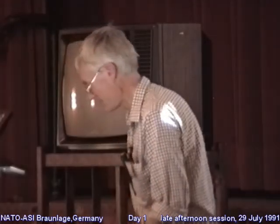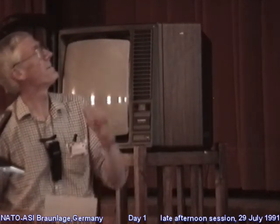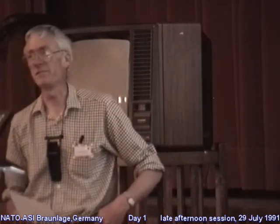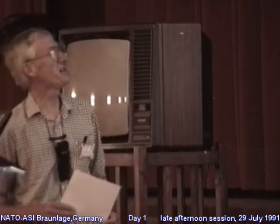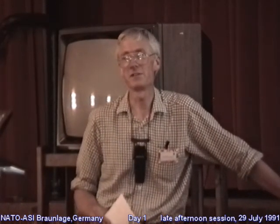There is an expression that is taken from the paper by Maugis and Barquins. What we've got on the left is a kind of driving force for the inward propagation of this peripheral crack that I mentioned. G is the rate at which strain energy is released, not rate per second, but rate per unit crack area. G minus W, in effect, is the force tending to drive the crack inwards. And on the right, we have the drag. And the drag is actually proportional to W. It's proportional to the adhesion energy.